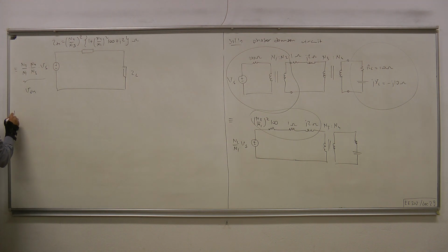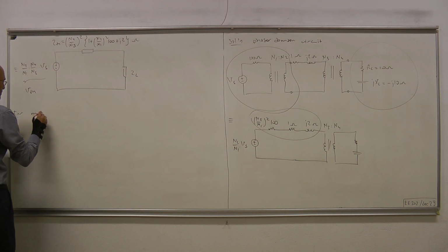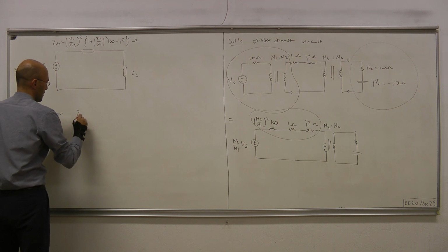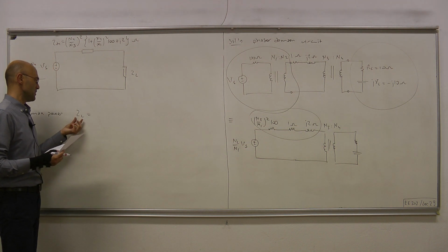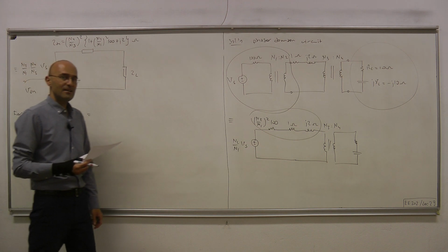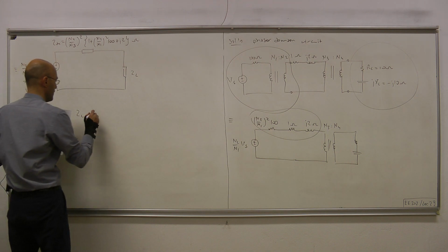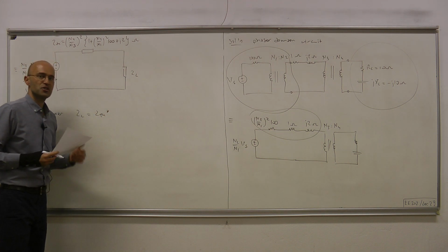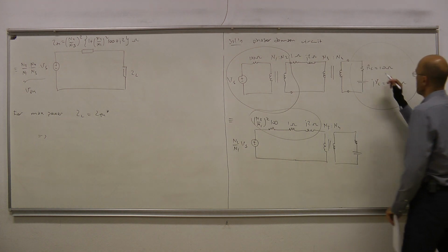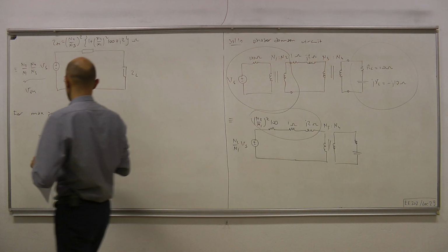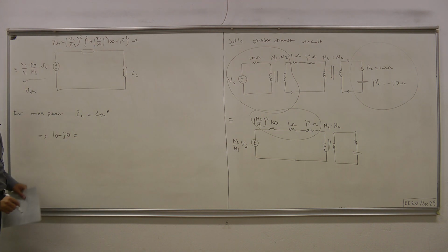Okay, so we have just obtained in the beginning of our lecture that for maximum power, when we can play with both real and imaginary parts of the load impedance, ZL should be chosen as equal to the conjugate of the Thevenin impedance. Okay, ZL must be chosen to equal Z Thevenin star. Therefore, ZL is 10 minus J10, and this must equal this thing conjugated.